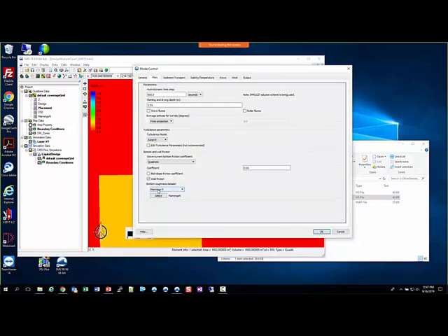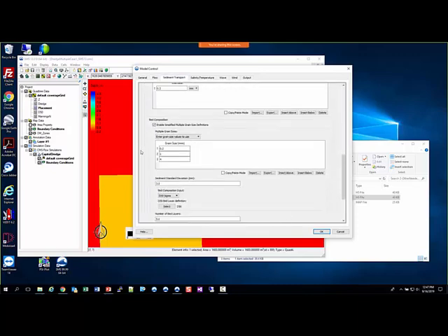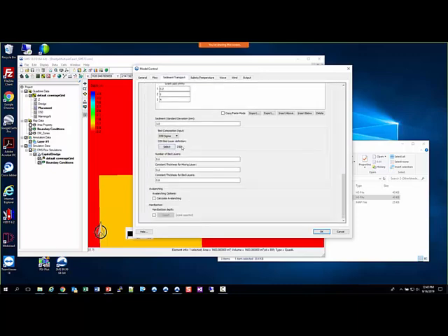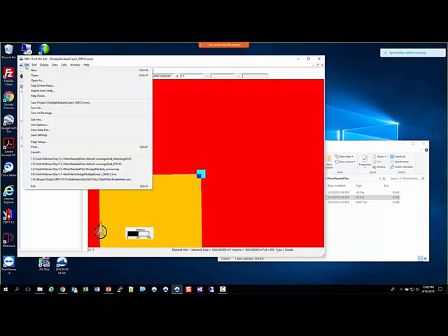So it automatically knows, it sees the Manning's n, so it sets up a Manning's n for your bottom roughness. And then for sediment transport, it sees I have a D50, and so it sets that up as the D50 data set. And so I should be good. I click OK here. I will make sure I want to save the project.